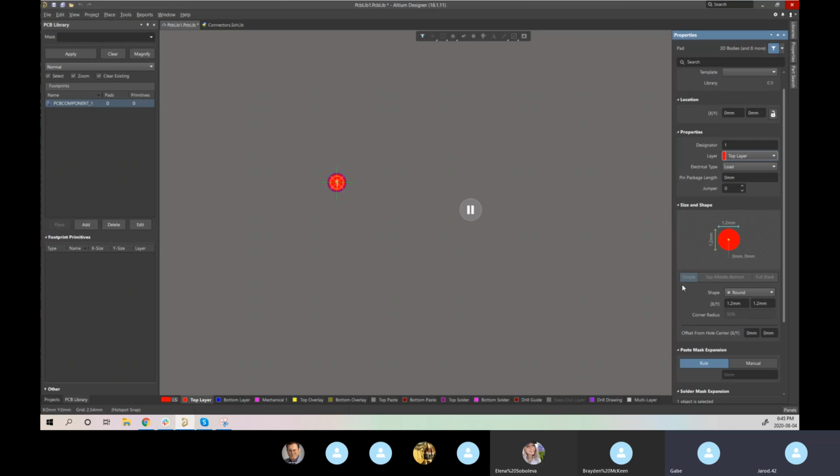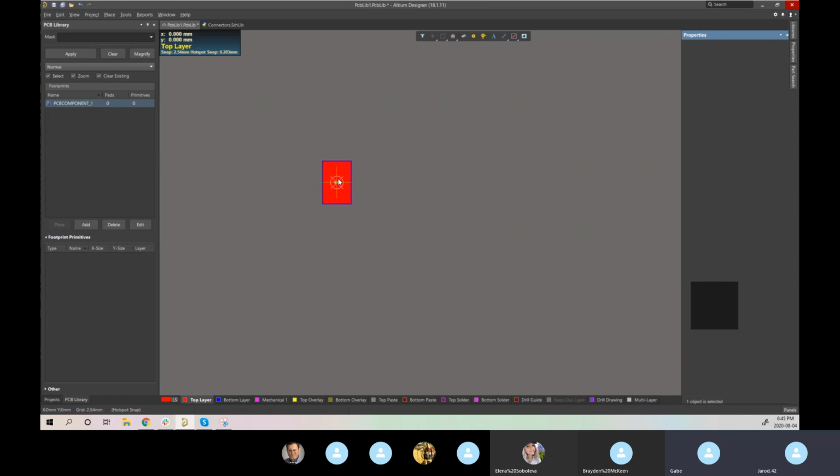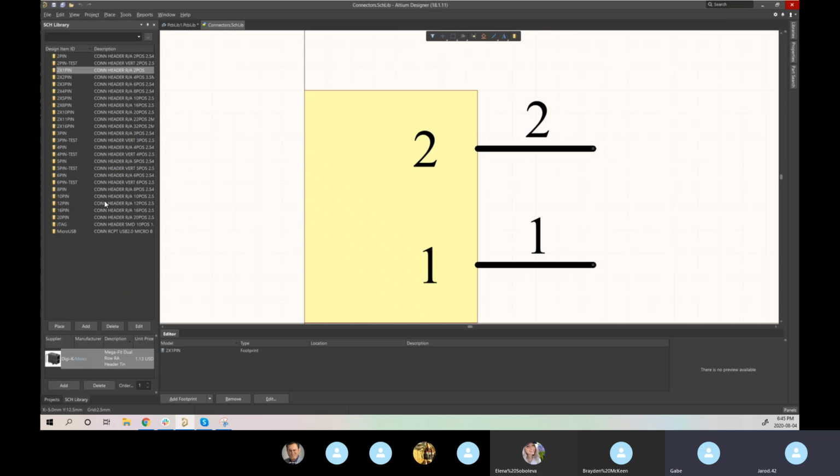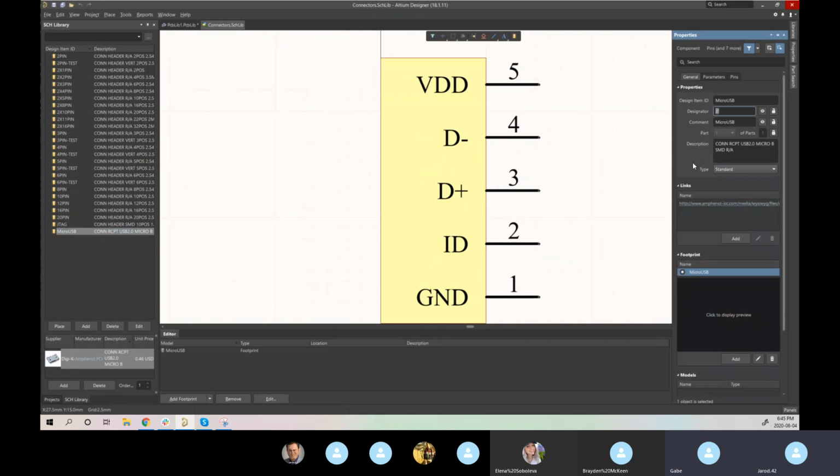Now, typically your surface mounts are going to be rectangles. You would just go about changing your X and Y based off your pin length. So we'll say 2 and 3 for right now. Here, let me pull up, I think this was a surface mount one.